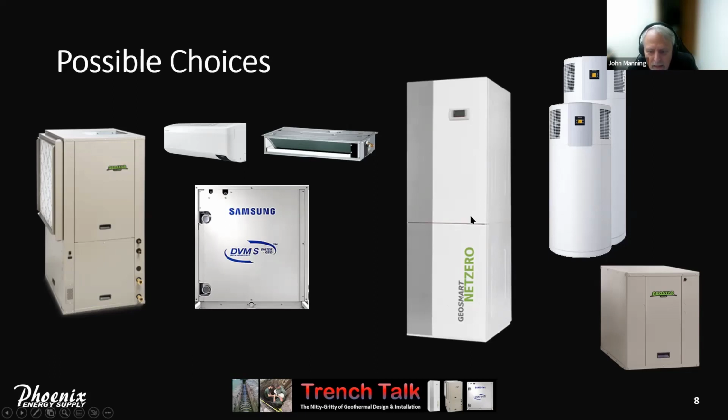This particular heat pump, the net zero, has the ability to also do 100% of the domestic hot water built into the heat pump itself. So if we don't go with the net zero and we go with either Samsung or Geostar, the other technology we would employ to look at domestic hot water is either an air-to-water heat pump that heats the water in the tank, and as a secondary benefit, it would cool or dehumidify the space where it's located.